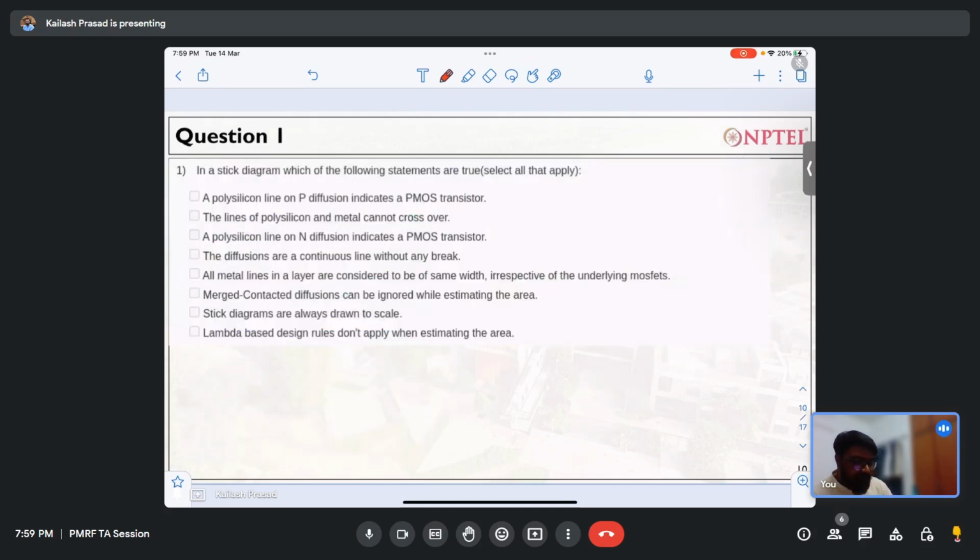Okay, if you do not have questions, then I have questions. We have taken maybe 50 minutes to understand the layout itself, right? You might have seen how the layout looks in the third dimension, how it looks from the top, and what the things in the layout are, when I'm talking about metal, diffusion, active, contact, and where each actually sits. We have seen a couple of processes like photolithography, where you have to cut and remove, and because of all these steps there can be variations in the circuit itself. We call this process variation. We have also seen that there can be voltage and temperature variation. So whenever you design a circuit, it should be PVT tolerant: it should work across process, voltage, and temperature variation.